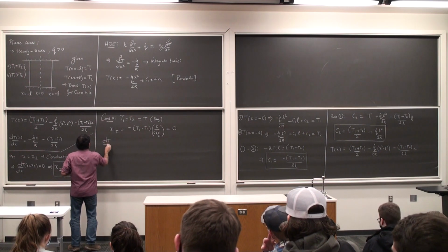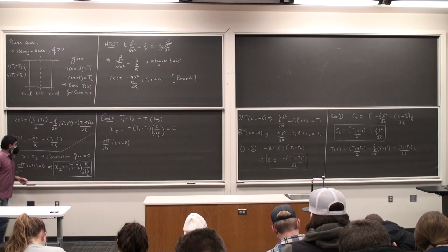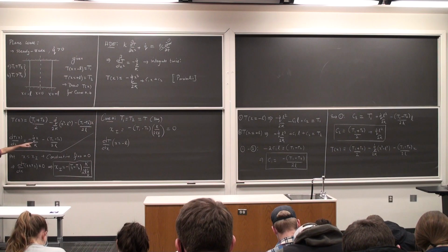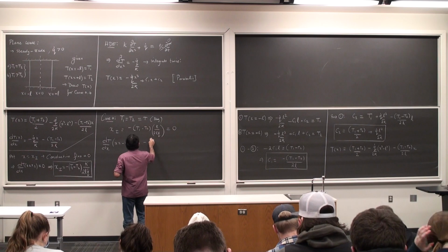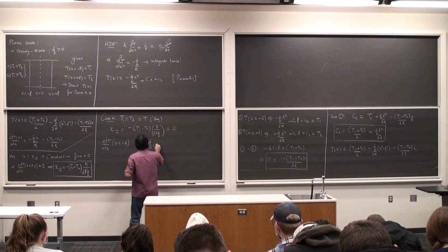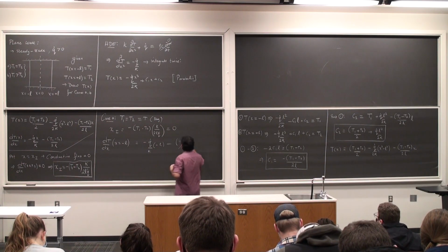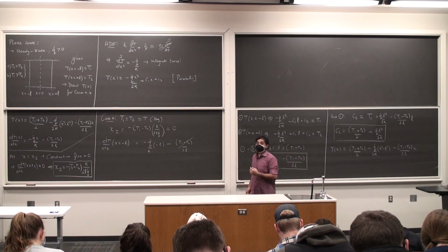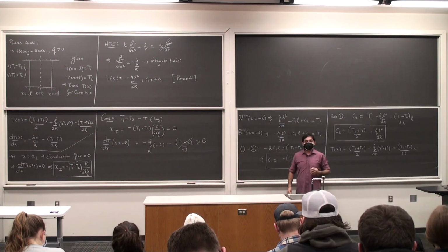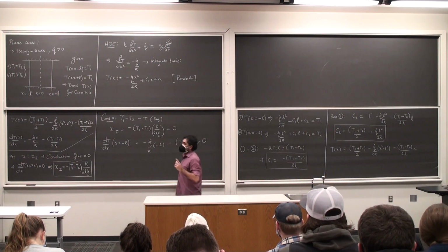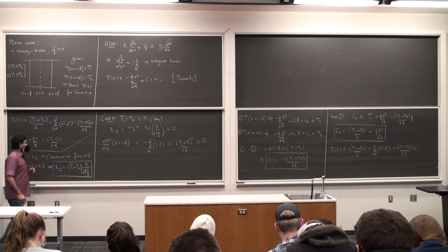So calculate the derivative at x equal to minus L. Do the substitution. So (T1 minus T2) by 2L is 0. So this just becomes minus Q dot by K times minus L. That's 0 because T1 is equal to T2. So this becomes a positive number. Exactly what our intuition is leading us to believe. Remember, if heat enters, it has to get out of this stuff somewhere. It cannot linger around. It's not a vandal.